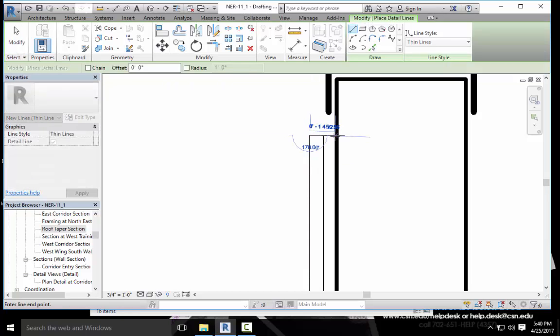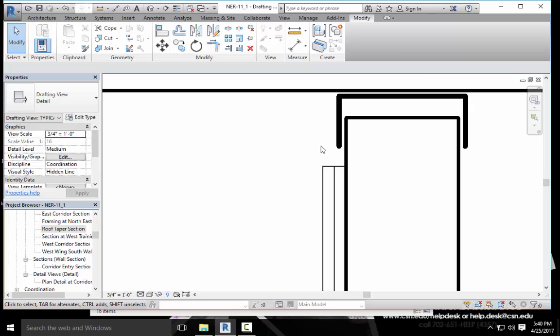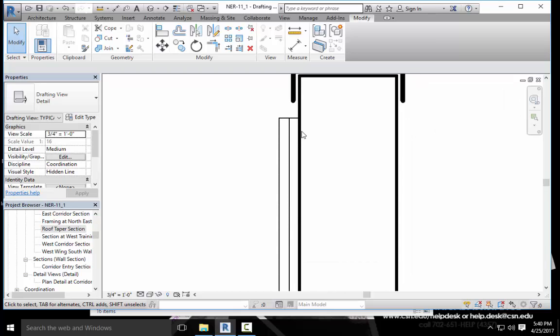And if this is a fire rated partition, another piece of drywall is put on the outside of that track so that it can still slip. Does that make sense? Because the floor above actually deflects. That's why this detail is made the way it is. So that's one way to add the gypsum board by doing an offset.